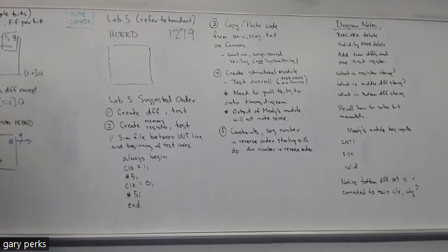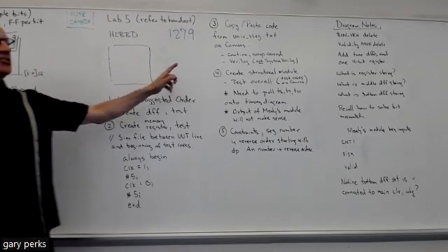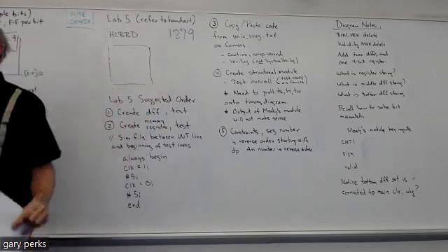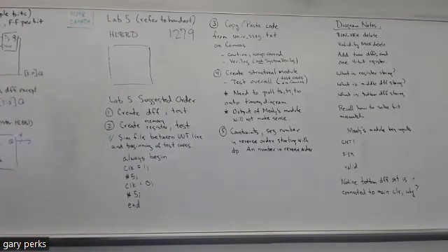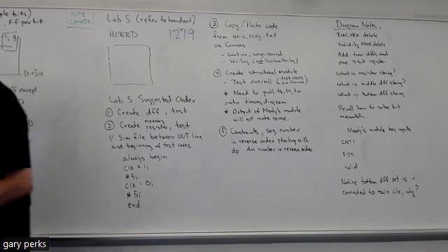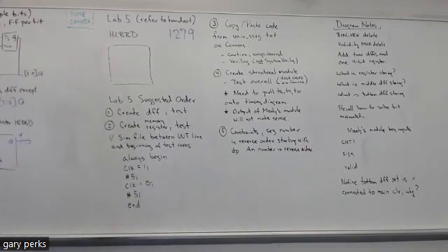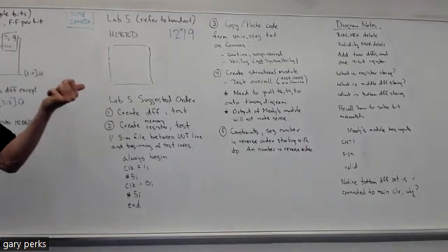Okay, so there's half a dozen main differences. There's probably other ones that aren't as common. But the key thing is, for this lab 5, just make sure that you create a Verilog file for Mealy's code. You see, Vivado will run mixed files. Like all your design sources, like your flip-flops, your register, the top module that you use to connect this all together, that's all going to be in System Verilog like you've been doing. Okay, and Mealy's module is going to be the only one in Verilog. But Vivado will run mixed files.